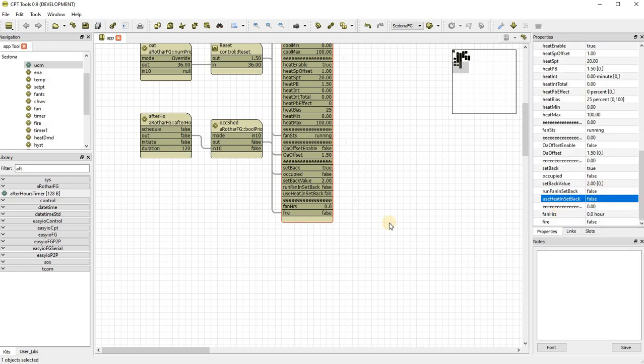Then we have the use heaters in setback. This is more for electronic heaters or electric heaters, not for boilers and things. If you've got a boiler, it's probably cold where you are. Electronic or electric duct heaters are quite inefficient in their energy consumption. So in an area, subtropics or tropics where we live, you might want to exclude heating.